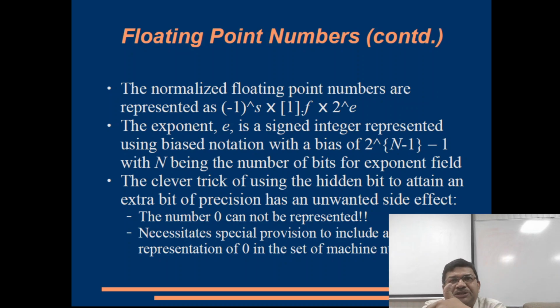Not a very difficult thing to do, right? So for this floating point operation, exponents will either be added or subtracted. If they are subtracted, bias needs to be added, and if the numbers are added, then bias needs to be subtracted. That's all. That's a very small compensation that needs to be done, and all is taken care of.